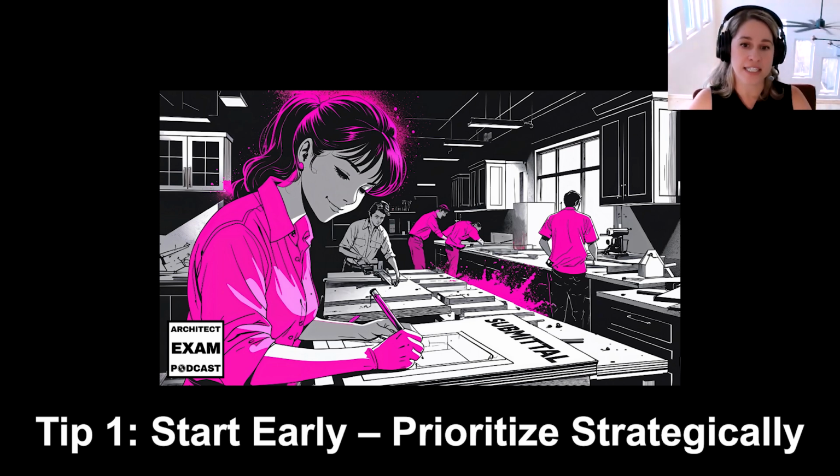Next, you'll prioritize submittals that have a very long lead time, or that if they arrive not on time, it would delay construction activities. So usually windows and doors have a long lead time, building system components like HVAC, or maybe elevator or conveying equipment have a long lead time. I always recommend front loading the process and aiming to have at least 80% of the submittals approved before construction even begins. That way you can start ordering these materials, curating them to be on the site and ready for installation so the project can keep moving.